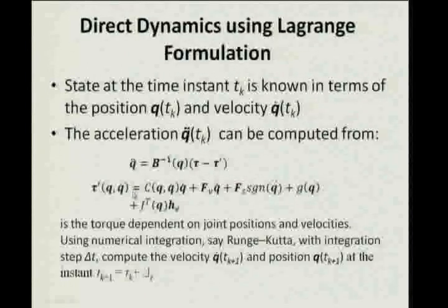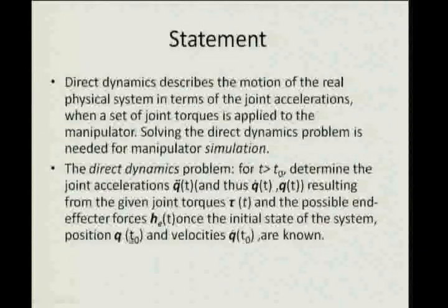So, this is a very simple formulation. Okay. So, but for this, when I calculate this T prime matrix, I am using q and q dot at the present value, at the present estimate of q and q dot, which is okay. Because when I start, if you look at the definition of this problem, when I am starting, I know q and I know q dot T0.